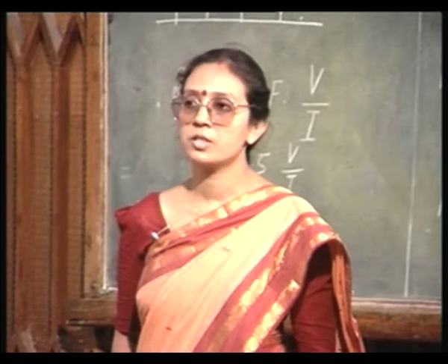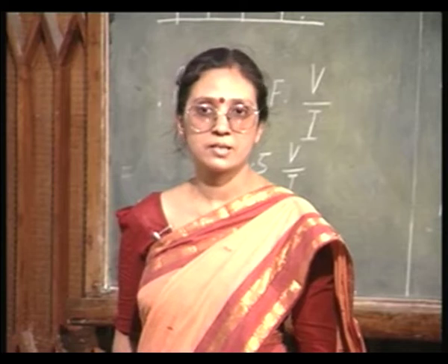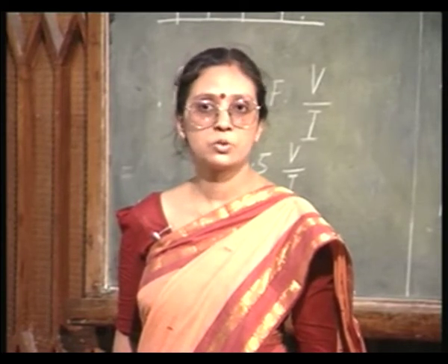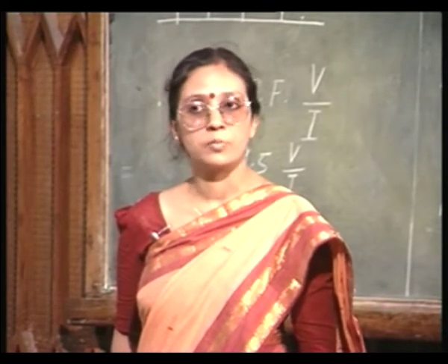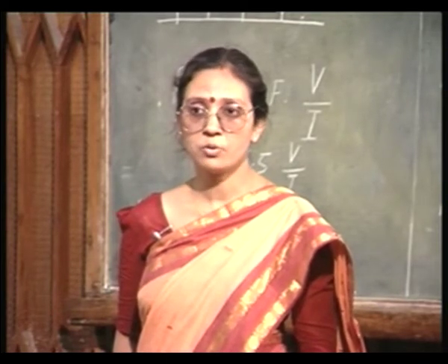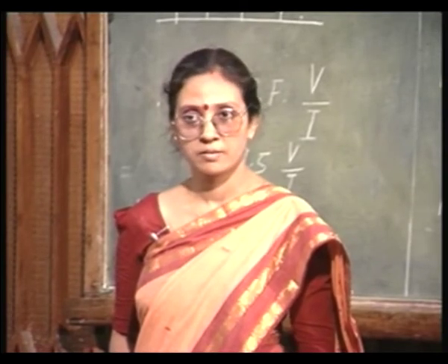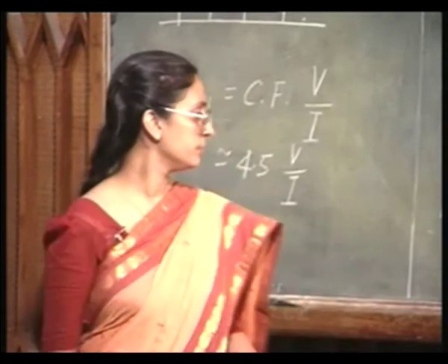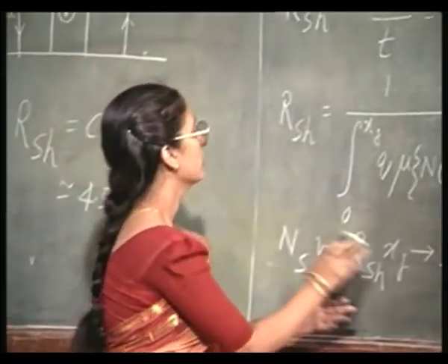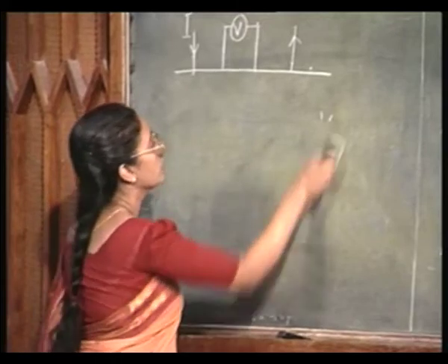The depletion region width is going to increase. So, the change in the capacitance can be related to the change in the depletion layer width. From this you can find out what is the change in the charge. Okay. So, from the CV technique also you can find out the doping profile,